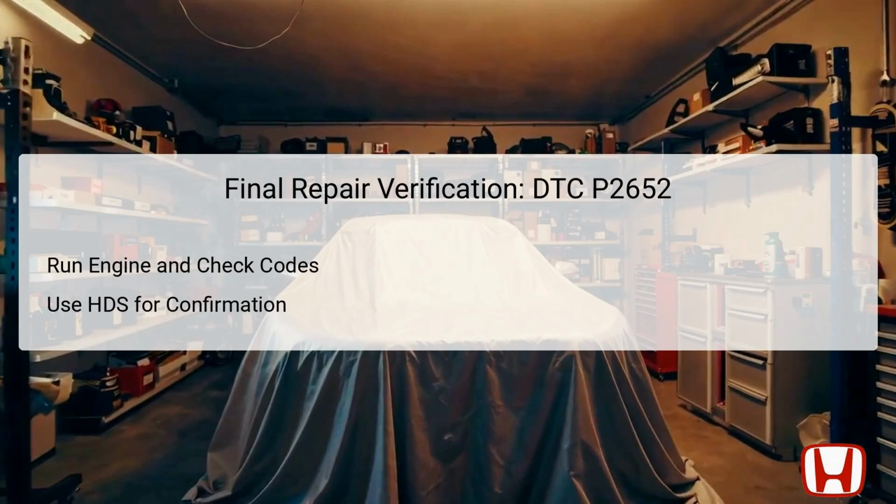This advanced diagnostic tool provides insights into the status of the vehicle systems and confirms whether the DTC P2652 has cleared. Monitor the values for the rocker arm oil pressure sensor to check if they align with expected normal conditions. If the code has been successfully cleared and the sensor displays normal readings, this indicates that the corrective actions taken have restored the system to optimal functionality.